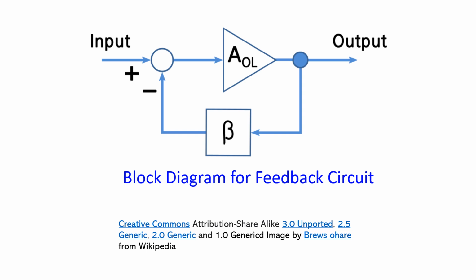Automatic gain control reduces volume if the signal is too strong and raises it when the signal is too weak. The feedback control signal is usually taken from the detector stage of the receiver and used to control the gain of intermediate frequency or RF amplifier stages. Appropriate filter circuits are needed to prevent the audio component of the signal from the detector stage producing distortion by overmodulation of the received signal.